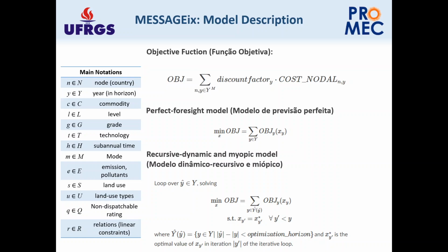So you say, if a hydropower plant has a flooded area higher than 1,000 square kilometers, we are not going to build it. So this is a restriction that you can put in the model, and then it's not going to build a hydropower plant which is bigger than that flooded area. And you can give characteristics for each of the technologies, for each of the hydropower plants that you have, and the characteristic you put is flooded area, and then you have a restriction. Let's say flooded area higher than this area is not considered. So you can model this.